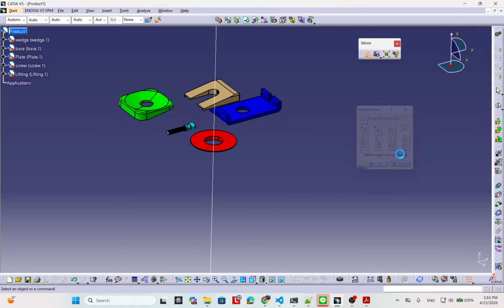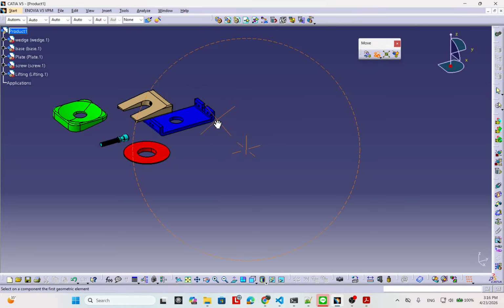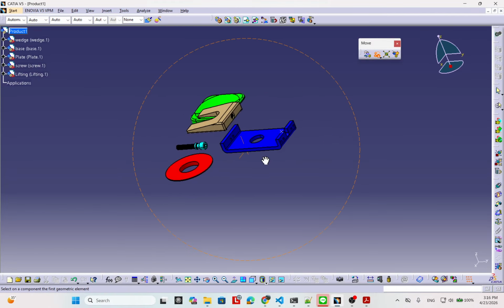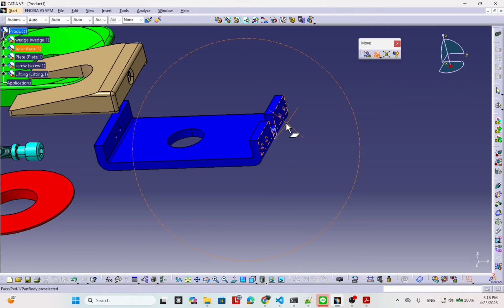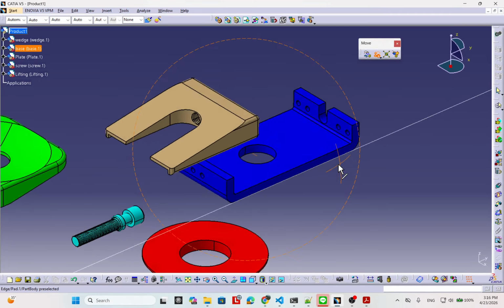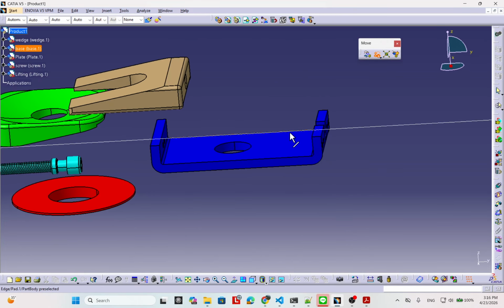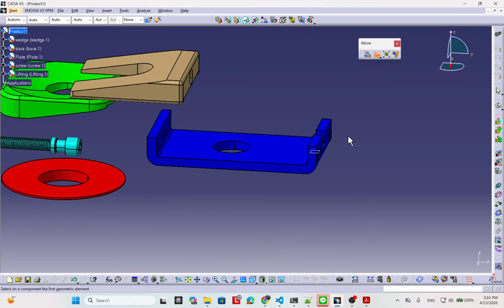Next toolbar, the command tool, and this one is Snap, right? Snap lets the program calculate the condition for your part. If you pair this one and this one to assemble each other, the program calculates what kind of condition both parts use to connect each other.